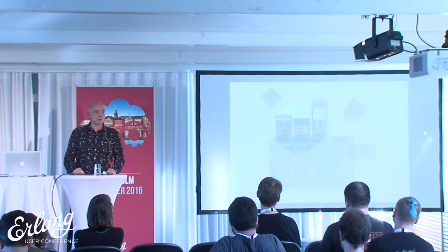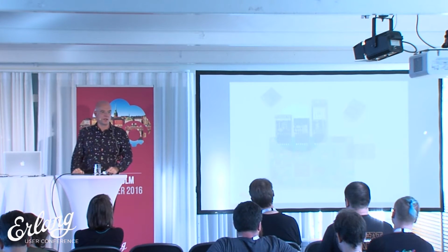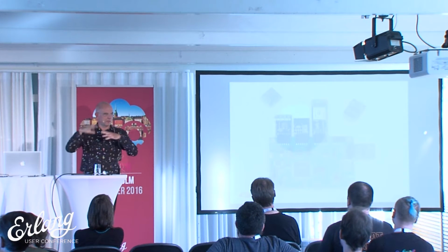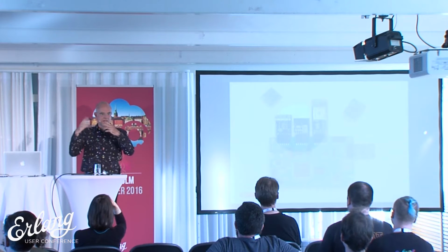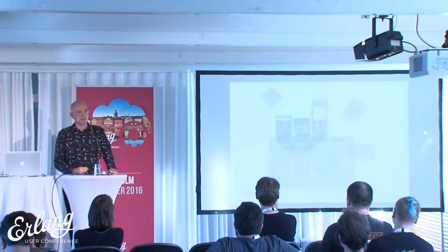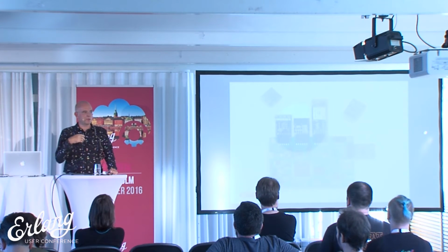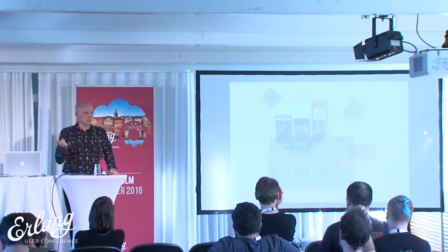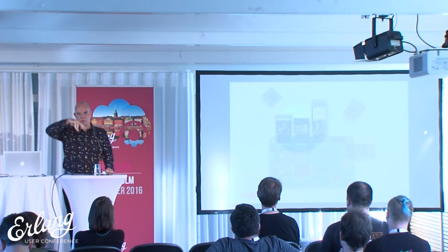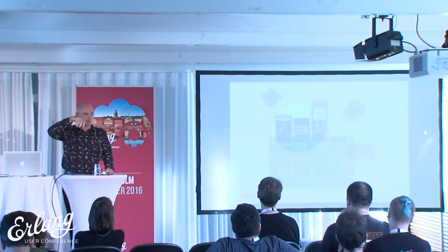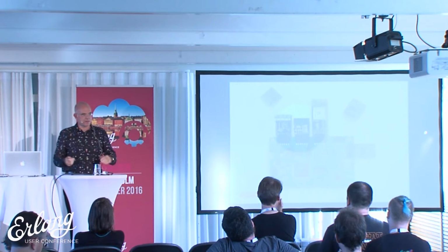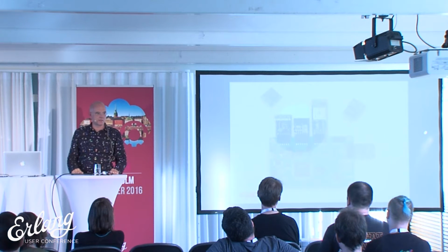The next thing is also for motors. It has connectors for 4 standard RC servos, which are used in model planes and stuff like this. So you can just get one of those and plug them in, or 4 of those, and then basically you have some pulse width thing going on. It's for GPIO. That's one of the reasons you need these pulse width things, because this actually controls where the servo moves to, so you can control the angle. It's very easy to use, and you can do lots of fun stuff with those.